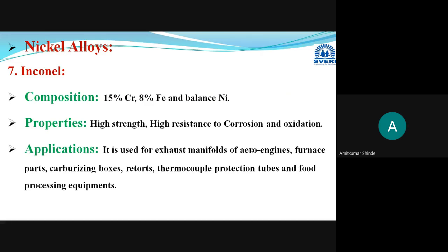Now, Inconel is an alloy with nickel as the parent metal, and chromium and iron as alloying elements. Here chromium is approximately 15%, and 8% iron will be there. It shows very good, high strength, and higher resistance to corrosion and oxidation. Okay, and their applications are like this.